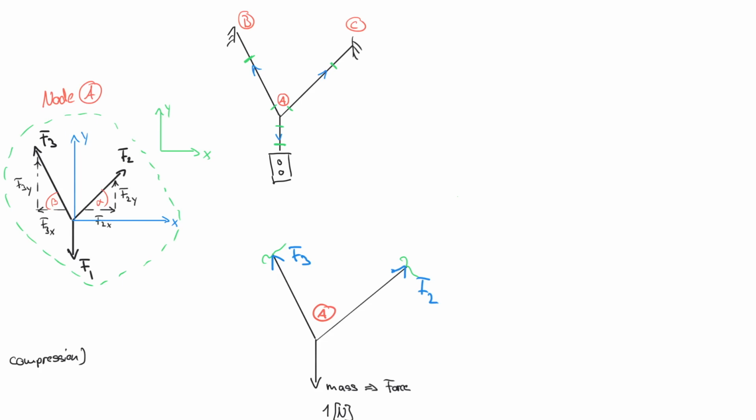And the reason I'm repeating myself here over and over again and explain this one more time in a free body diagram, the real world, and then developing the free body diagram, is because this concept here, where I cut it first and then I bring in the forces, is so important, because that is the trick that engineers always use. So engineers really always check, like, what happens if I remove the force that holds it in place.